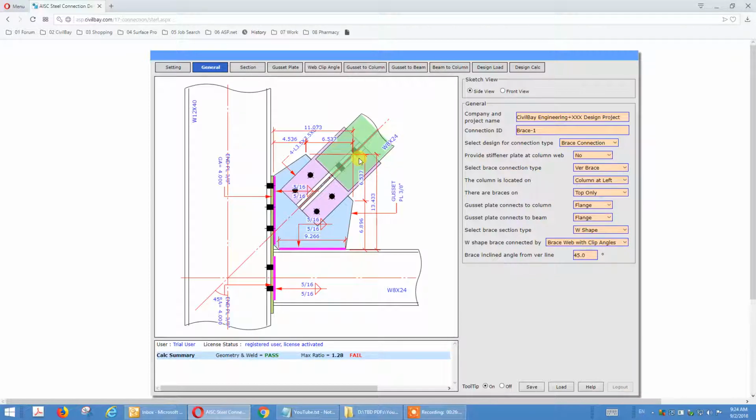And also the other way we use this type of connection is for horizontal brace. We want this wide flange web to be vertical. If you go with the web horizontal, in the horizontal brace case, it will accumulate water. You have to provide a drain hole, and it accumulates dust. So two cases, okay, we use this type of connection. One is the X brace, cross brace, X cross brace.